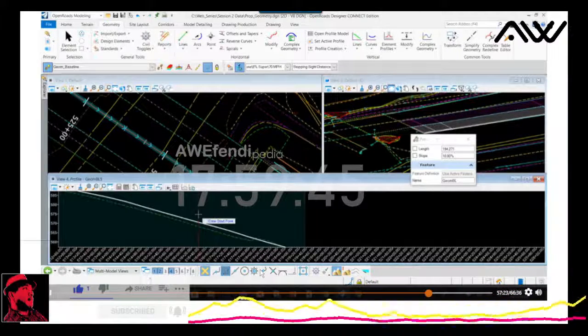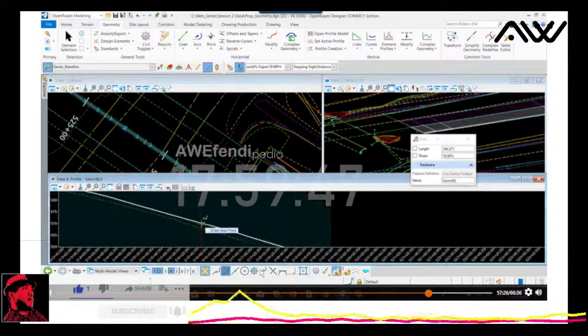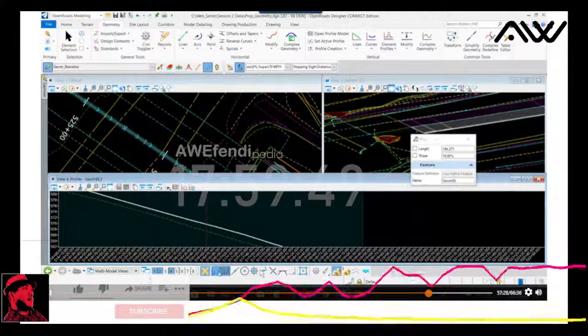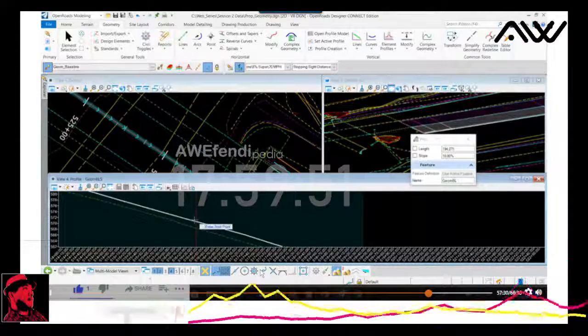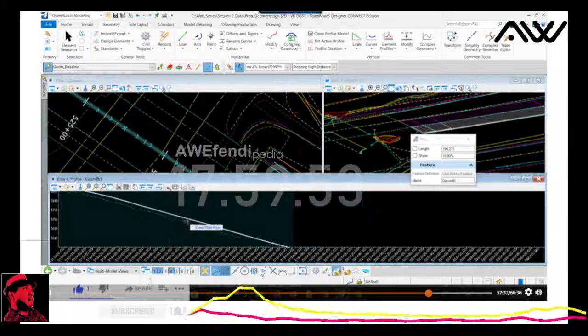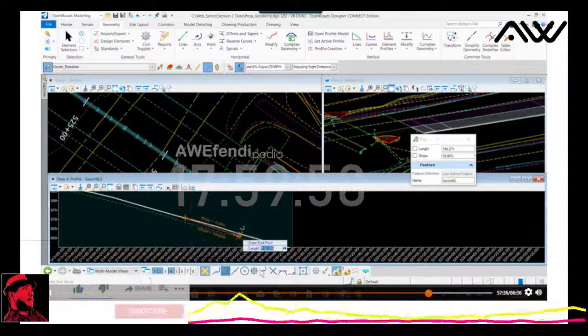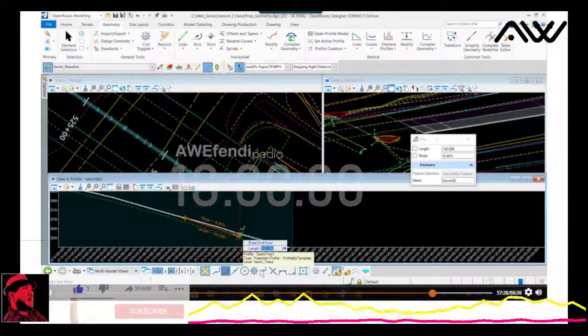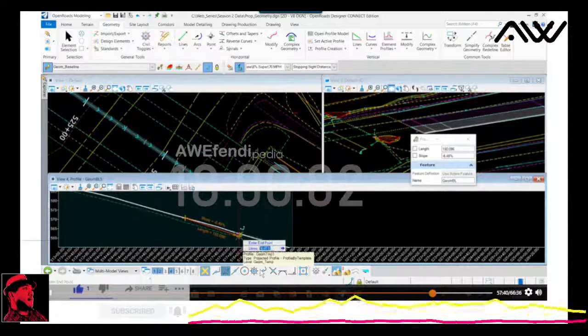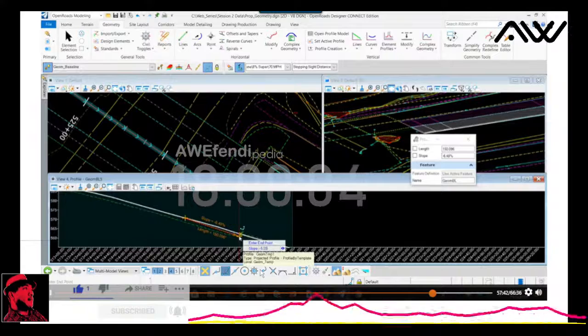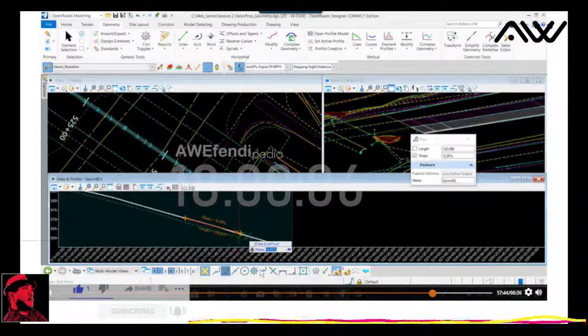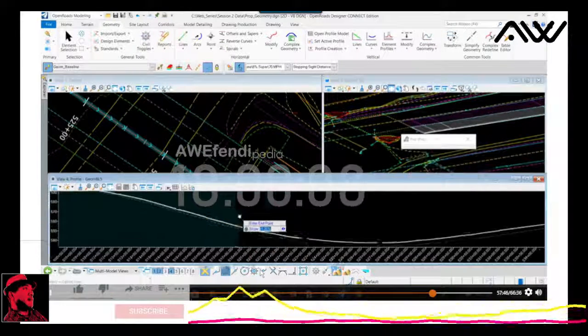And then I'm going to go down. I'm going to click, and I'm going to follow along. Again, I'm just snapping so that I follow along this graphic, and I'm going to create the next tangent segment. Okay, the next tangent segment, as I draw it out, I'm pushing the right arrow, and let's hold to 5.25. And then, again, we're sort of just graphically inputting these values.